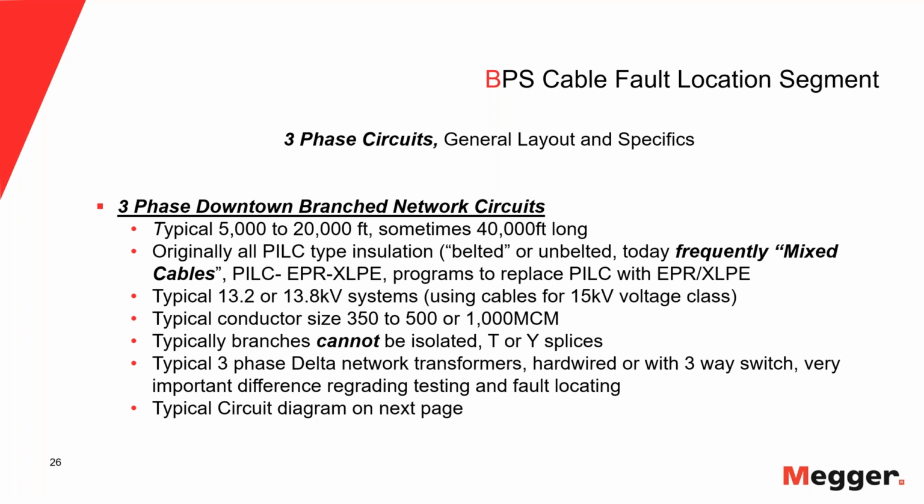So the reality is, in many of these systems, you have a mix of cables. You have old paper, it could be belted, unbelted, or both. And you could have EPR and XLP spliced in. So you have really a mix of different types of installations. And that's important to understand.